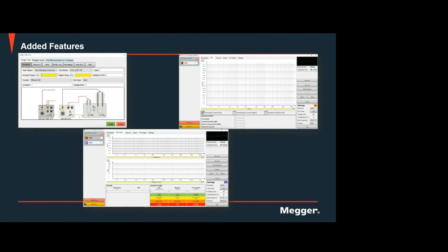So you can do DFR measurement, you can do DFR with ITC correction, you can just do pure DFR, you can just do power factor or excitation current because you are already doing 2 kV. So you can now do the excitation. And you have the PDC moisture, PDC ITC1, and the PDC. So if you select PDC here, it will bring you to this display, wherein it will give you the PDC value. So here, you can already have it using just the IDAX322.